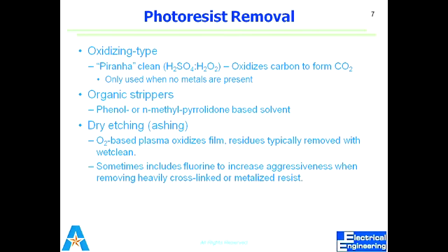Dry etching. Whatever we have used up till now is wet etching. Whenever you have a chemical and you dip your wafer inside to clean the surface, that is a wet chemical etching or a wet cleaning process. Dry etching is also used for cleaning the wafer surface. In that case, we use an oxygen plasma, that is, oxygen in ionized form, which is used to etch a very thin layer of the wafer surface. So we name it dry etching.